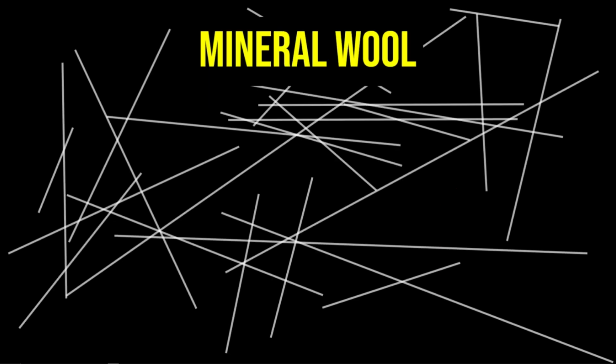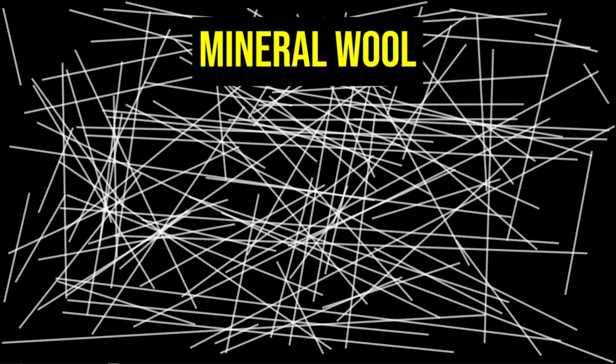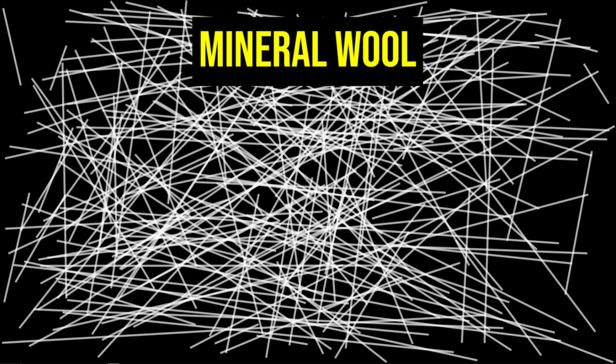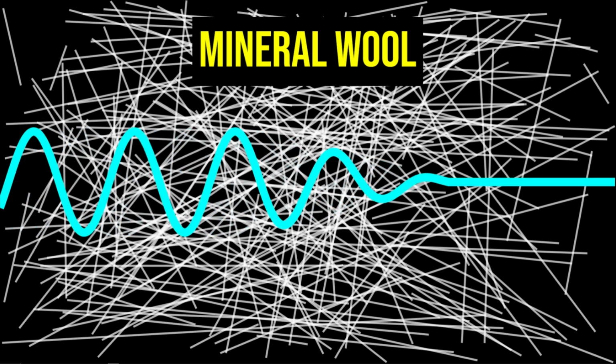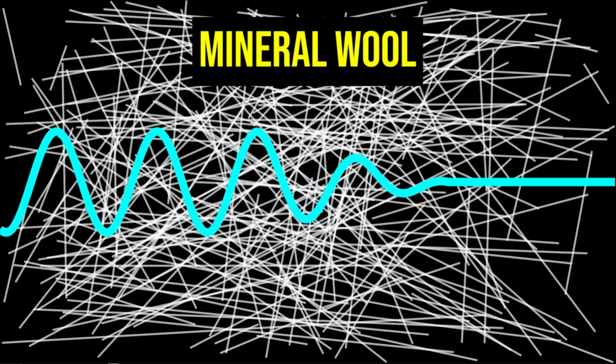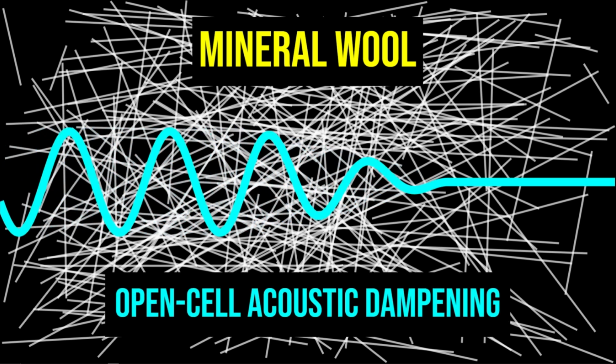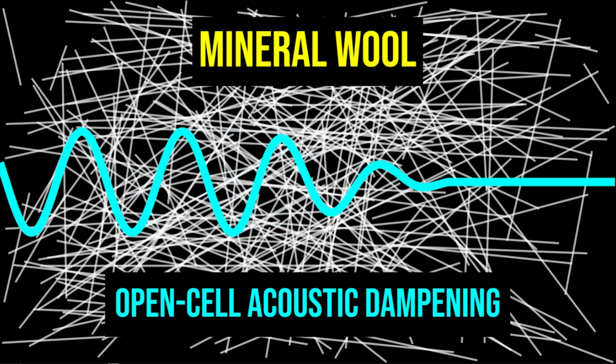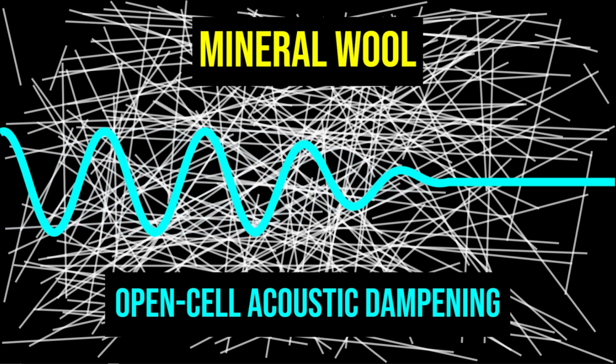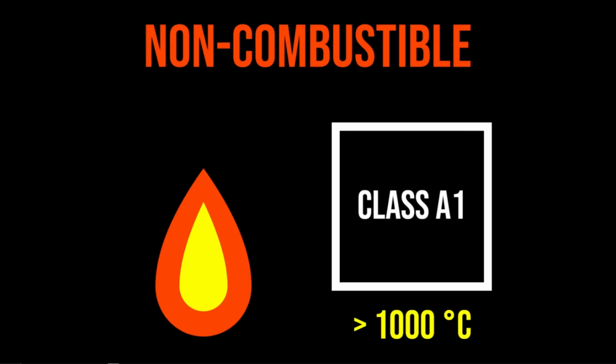simpler expansion methods. Mineral wool, encompassing both glass and stone wool, functions through a completely different physical principle than plastic foams. It is produced by spinning molten glass or volcanic rock into fine fibers, which are then bonded with a thermosetting resin. This creates an open-cell fibrous matrix that excels at trapping air while remaining highly permeable to water vapor. The random orientation of these fibers provides excellent acoustic dampening properties, as sound waves are dissipated into heat through friction within the dense fiber network.